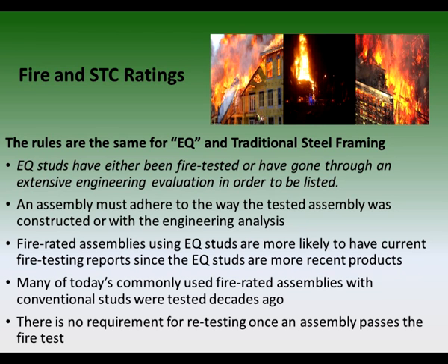With fire and sound ratings, the rules are the same for EQ members as they are for traditional or conventional steel framing. For fire-rated partitions, installation of the wall assembly must adhere exactly to the way the assembly was actually tested, or it is not in conformance with the tested assembly.